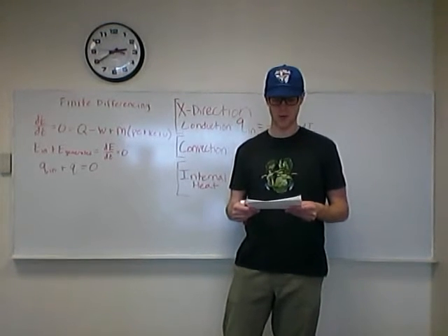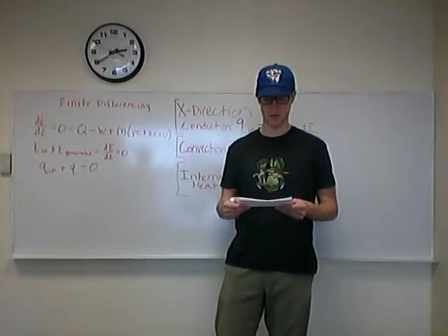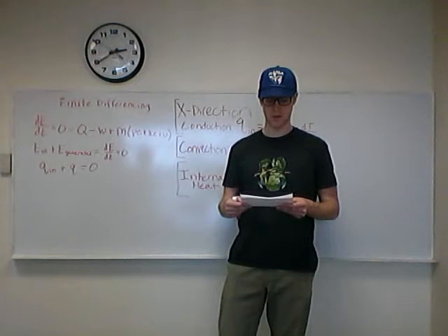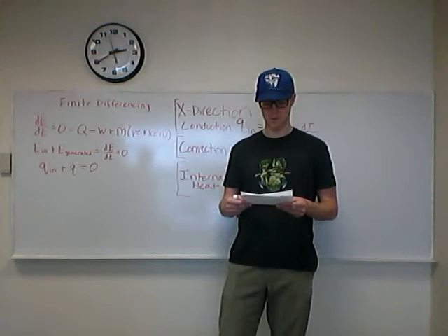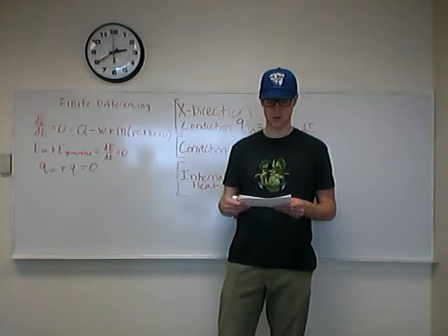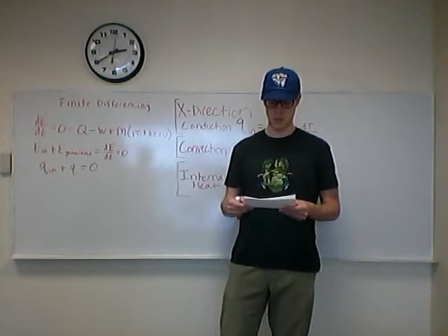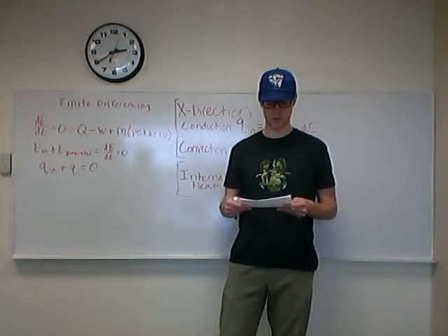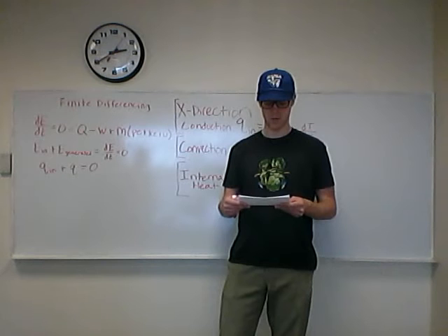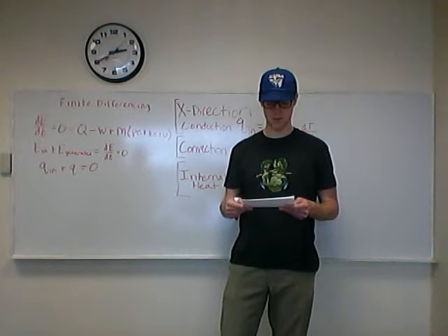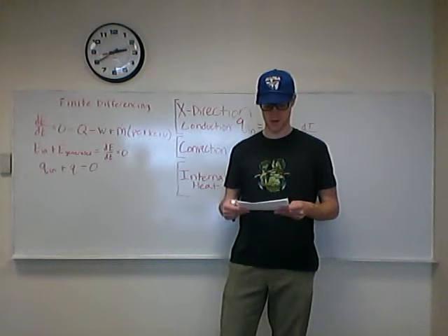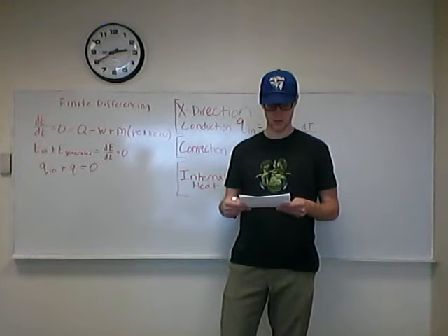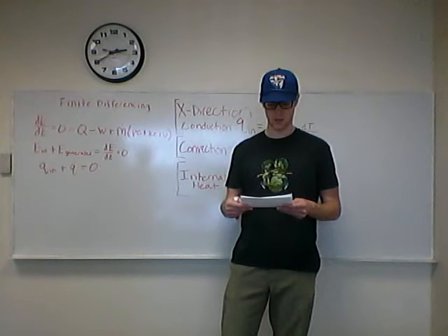Finite differencing is a way to calculate the heat transfer by conduction and convection by modeling the flow of thermal energy within solids, static fluids, and gases. In this video, we will be focusing on solids and the boundary between solids and gases. Because a non-uniform temperature field exists within a solid, a heat flux, or heat flow per unit time, can be measured. For our examples today, we will have our systems at steady state.